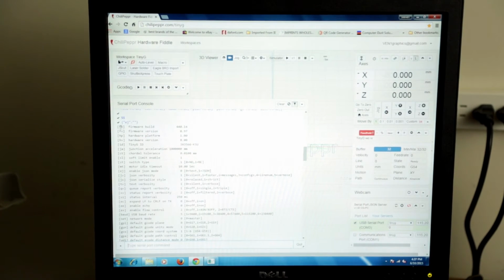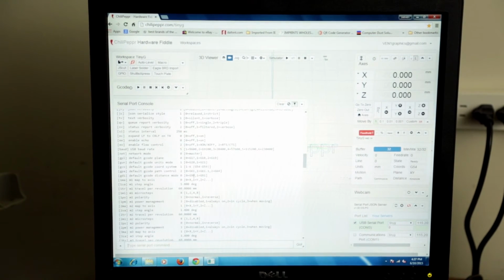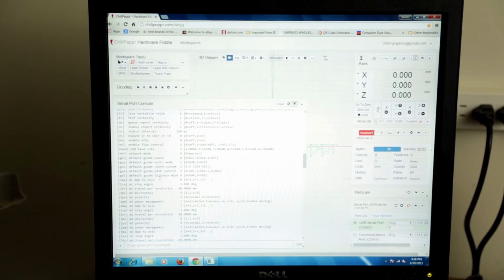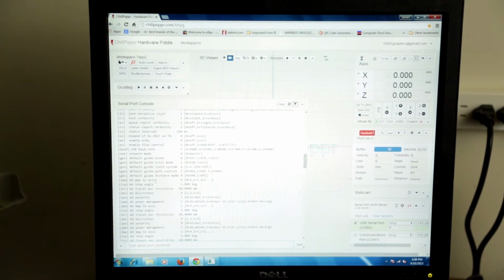Right here in these brackets on the left side, it's going to tell you some information. That's a code. So if I take $FB down here, it's going to tell me what my firmware build is. It calls to that. Each one of the motors 1, 2, 3, and 4, you see this number 1? All of these parameters from here to here are for motor 1, or M1, then M2, M3, M4. So our motor 1 is set up as 0, and 0 equals X. So to set up motor 1 as X, let me slow down a little bit.